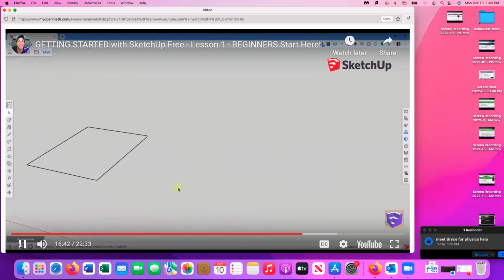And so one thing that you can do in order to make sure that you're drawing along those different axes is when you activate a tool, for example with the line tool, if I set my first point, if you tap either the left arrow key, the right arrow key, or the up arrow key, this will actually lock your different tools to the different axes.